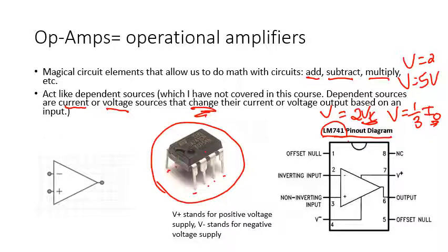So you first identify this by starting at the head of the op-amp where there's a notch, kind of like the head of your spider here, so you know which way to number your pins correctly. So starting from the head, the left-hand side pin would be pin number 1. So this guy would actually be pin number 1, then going down to 3, 4, and up on the other side 5, 6, 7, 8, like we have drawn here.